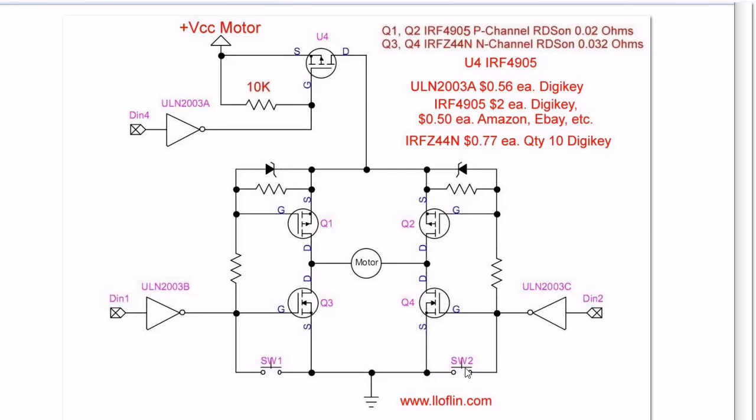Do the other switch with this one open, of course. This transistor will turn off. Q2 will turn on. Q3 is still on from before, creating a path through Q2, the motor, to Q3 to ground. So the ULN2003 provides a fair amount of isolation for the microcontroller, and it can switch a lot higher voltage.